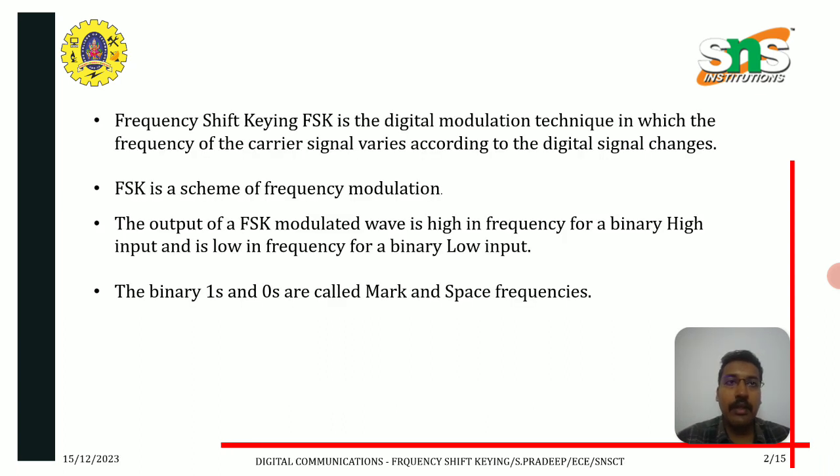Frequency shift keying is the digital modulation technique in which the frequency of the carrier signal varies according to the digital signal changes. FSK is a scheme of frequency modulation in which the output of an FSK modulated wave is high in frequency for a binary high input and is low in frequency for a binary low input. The binary ones and zeros are called mark and space frequencies.